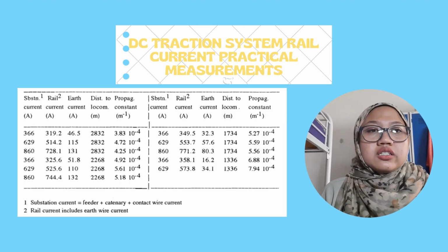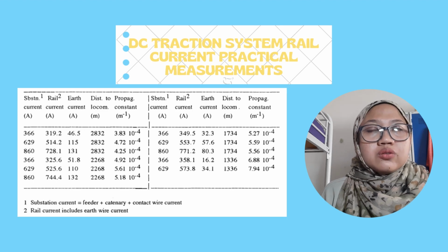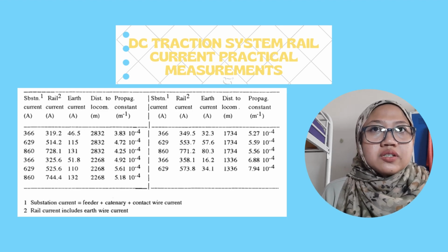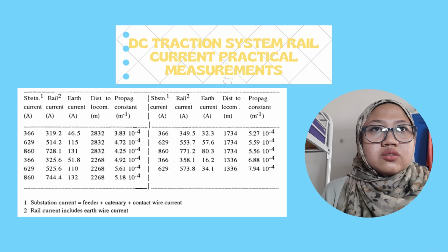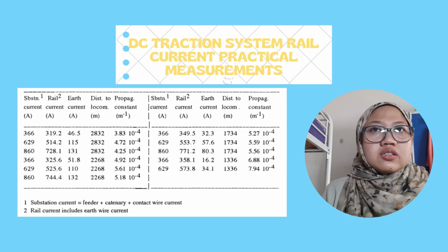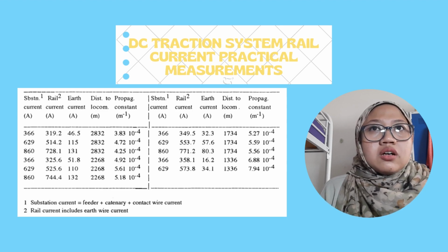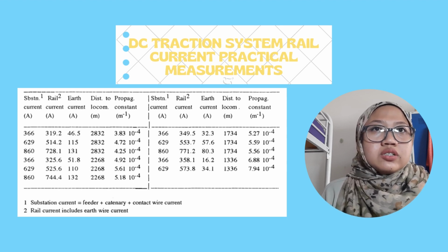From the test, here is the result. The variation of propagation constant with current in Table 1 could be due to change of ground condition during the test. So the interpretation using classic high-frequency transmission line theory, assuming a uniform, single-layer ground conductivity, yields an effective propagation constant, which decreases with increasing measurement section length.